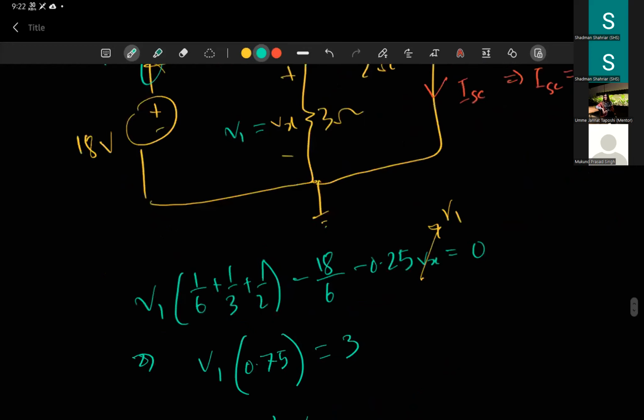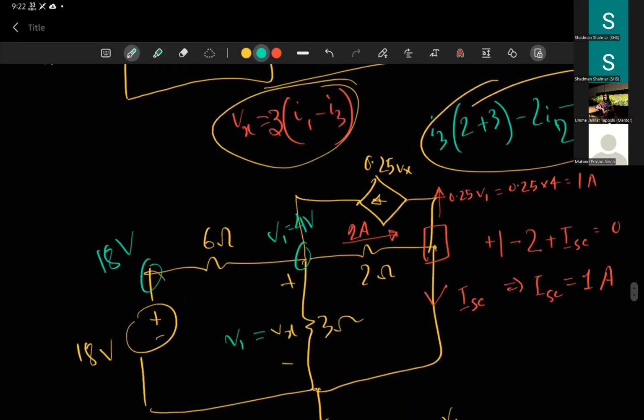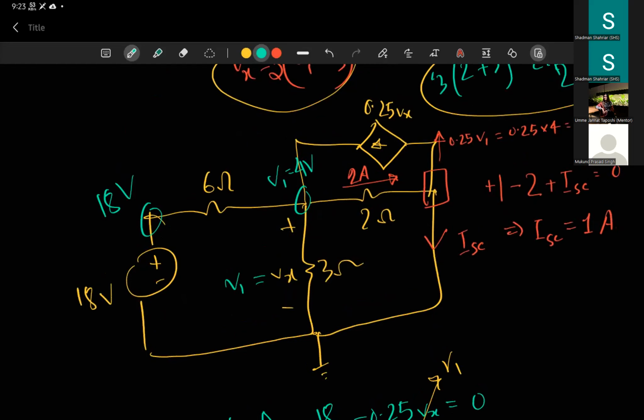I have a question. Is the ISC parallel with the 3 ohm, right? So we can find the voltage in the parallel combination. Okay, sorry, how does 2A become in the 2 ohm? Oh, how did I get this 2 amperes? Yeah. Here you have a 2 ohm resistor. What is the voltage on the right hand side?